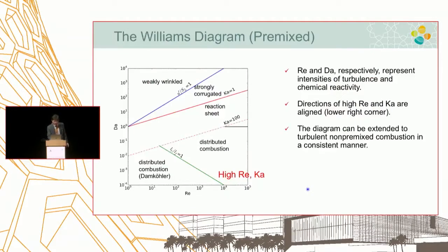So this is what happens, just to visualize, and this goes back to my earlier discussion of flame instability. The main microstructure of the premixed flame we are talking about depends a lot on whatever the small scale eddies do, which is a Karlovitz number effect.